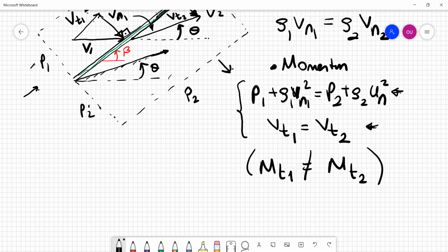What is the relation with rho and Mach number? The speed of sound changes, yes. Why does the speed of sound change? Because the temperature changes, static temperature, that is. Static temperature is different in any case across the shock wave, whether it's oblique or normal. How much does it change? It depends. In the case of an oblique shock problem, it depends again on the normal component of the oblique shock, how much the static temperature changes. We will see that equation.